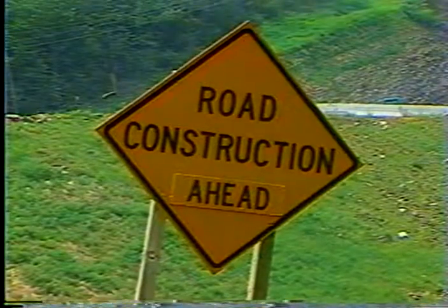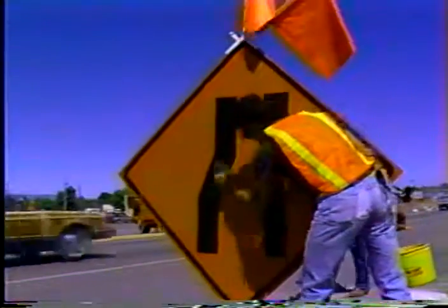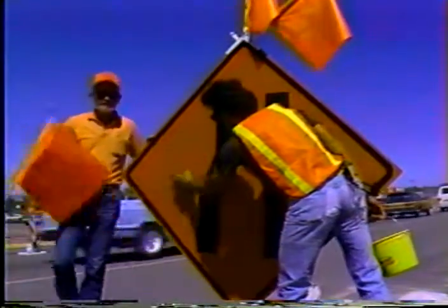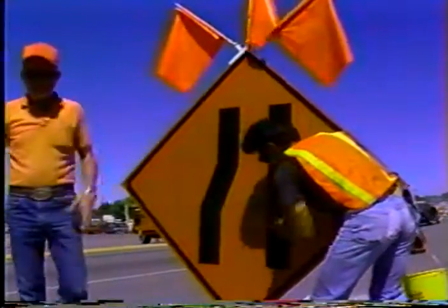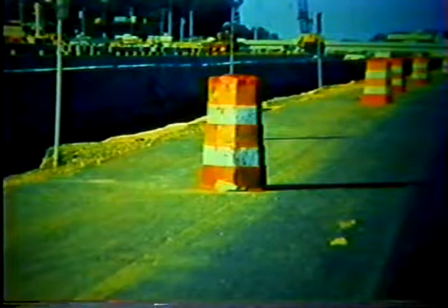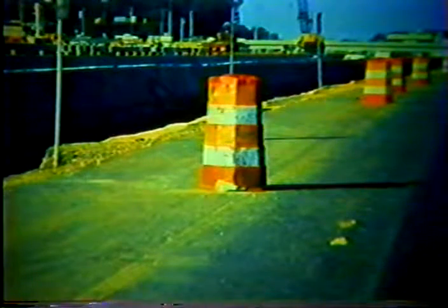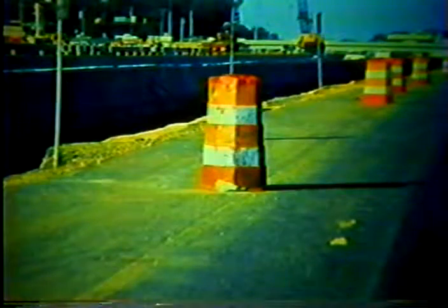The purpose of the device. Any device that's installed to warn drivers of upcoming hazards must be maintained at a high standard. When drivers don't receive adequate warning, accidents and lawsuits are frequent results. Also consider the overall system of traffic control and the role a particular device plays in the system. One dirty channelizer out of 100 on a daytime job isn't a big deal, but a series of poorly maintained devices that are supposed to provide nighttime delineation can't be ignored.